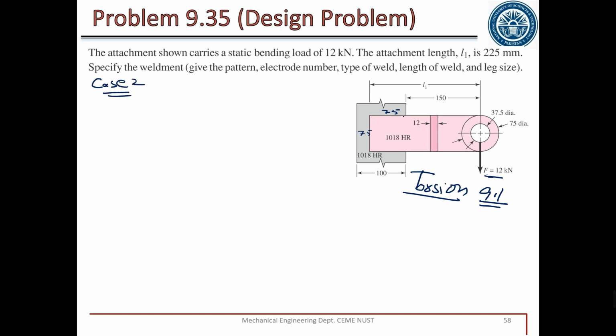I will assume that we will be putting a weld here and here because it had a rank of 1. So selecting this weld, the centroid will be exactly at the center. You can go and check the value in table 9-1, and this value is 75 by 37.5, 37.5 from the edges. So we have the value, and the maximum shear will be at any edge.